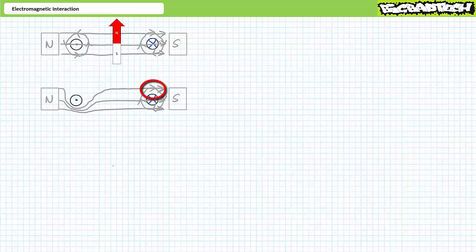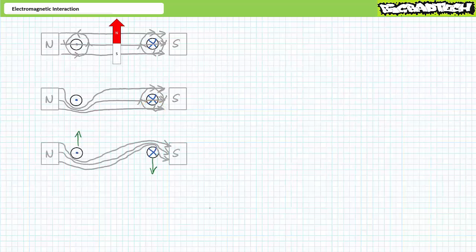Similarly, note the magnetic field on the top of the right-hand conductor is aiding, whereas the magnetic field on the bottom of the right-hand conductor is opposing. These fields coalesce so that there are fewer lines of magnetic force on the bottom and more on the top. The unified magnetic field on the top acts to push the right-hand conductor downwards.